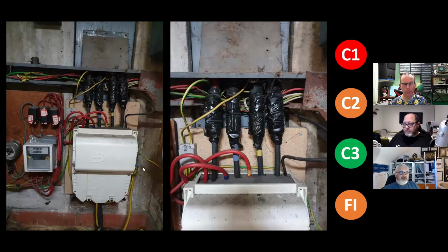Before we fail that installation, I think more time and effort and energy needs to be spent tracing those earth cables. So if you're with a customer, it's, look, I'm failing the installation based on the fact I need more time to ascertain and verify the configuration and the bonding setup and the earthing setup. And by the way, I need to contact the DNO and inform them that this is shite.